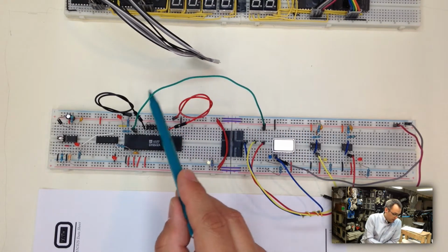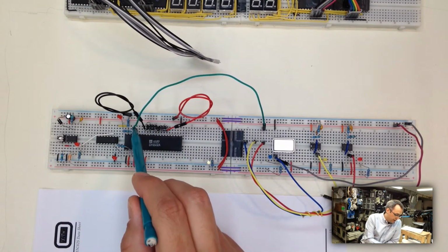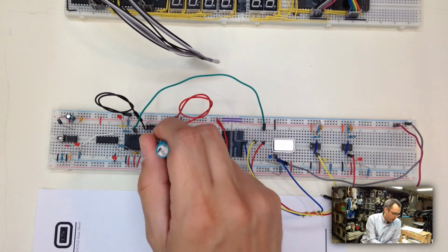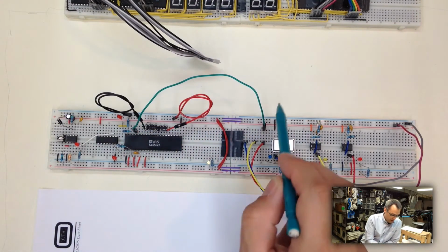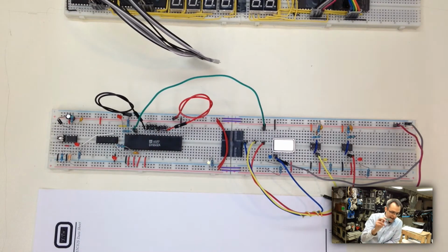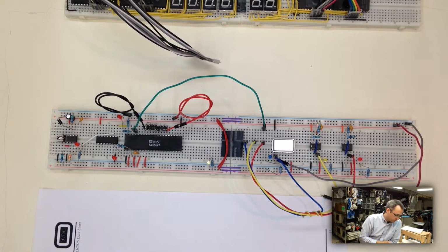This wire coming right over here is our phase 2 clock. This is the master clock that drives the oscillation and the operation of this chip. So I have that jumping over to this side board. Basically, when this receives a down transition, a falling transition, a positive to negative transition, it cycles the processor. Of course, this being the invert of that, when you turn this on, you can see those blink back and forth, like police lights or something. I don't know. I should have made that one blue. It would have been red-blue. That would have been cool. Anyway.